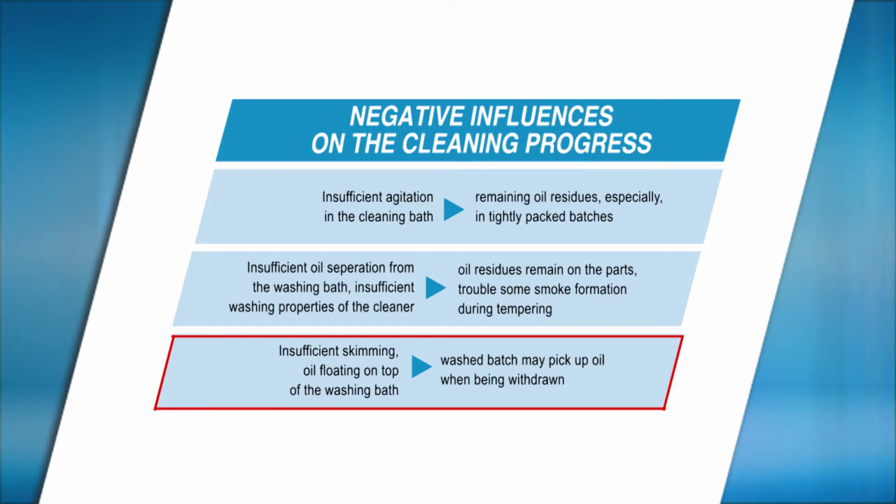The health of the cleaner bath is required to be ensured by proper skimming, so that the parts after cleaning do not get coated again with the oil layer floating on top of the cleaner bath.